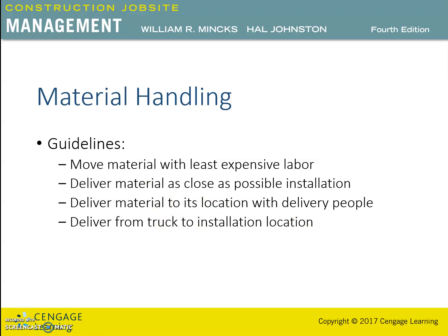The next guideline in material handling is to deliver from the truck to the installation location if possible. There are some instances when delivery can be made from the delivery truck to the material installation location. That is an ideal situation. This is often done with structural steel.